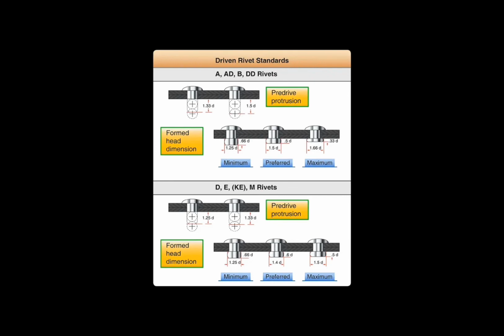What should you do to a drill bit before drilling plexiglass? Modified to a 60-degree tip angle, cutting edge to a 0 rake angle, back lip clearance angle increased 12 to 15 degrees. Modified to a 60-degree tip angle.